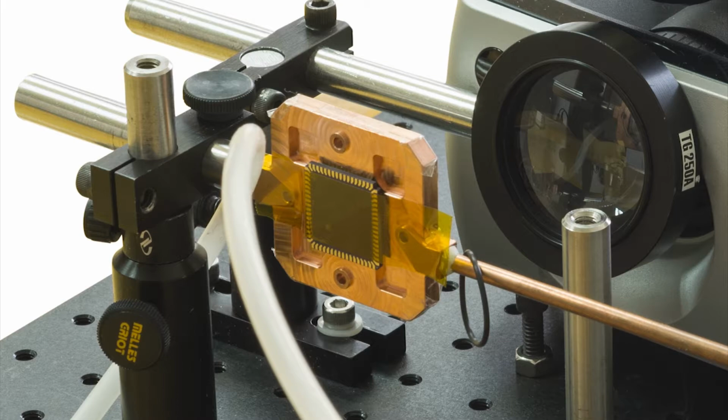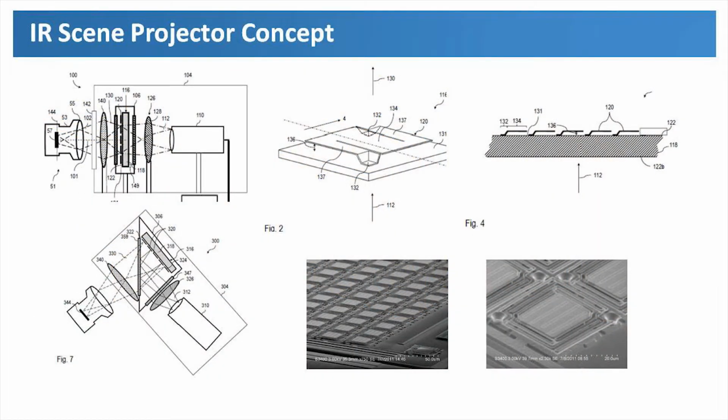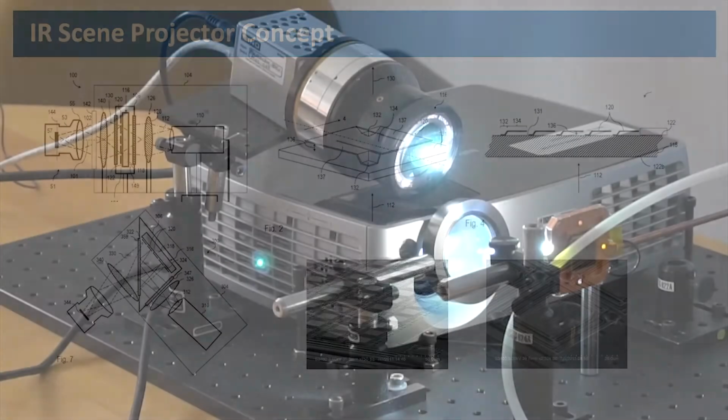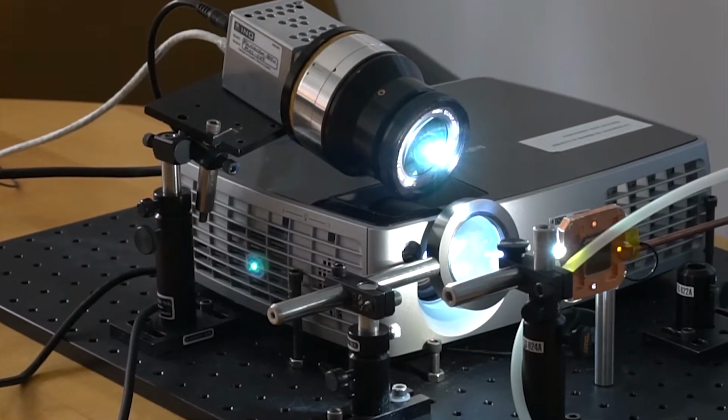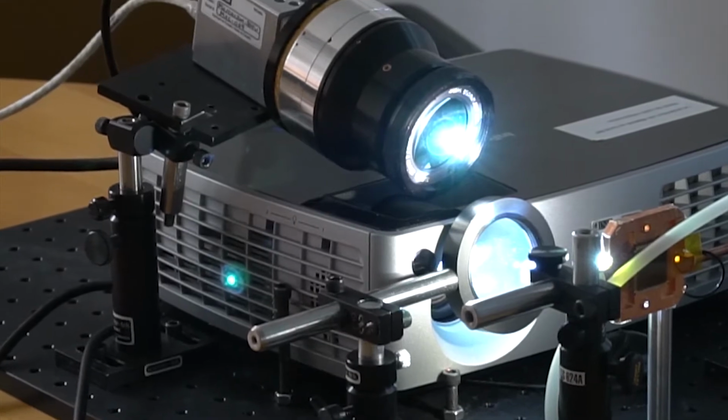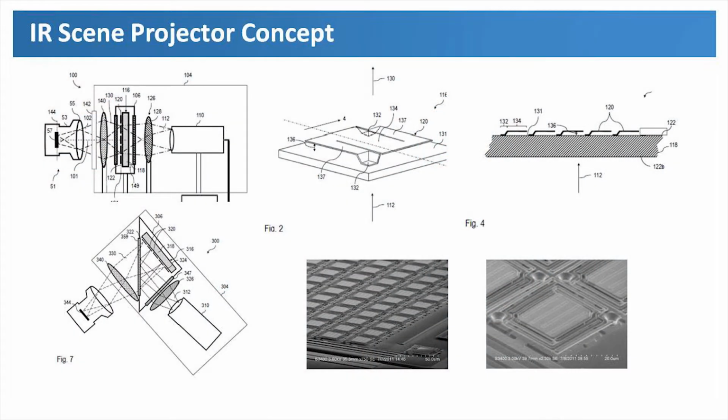So you have this micro platform which has a tiny size of 35 micron by 35 micron, a thickness of a fraction of a micron, and is supported by two legs which have a diameter in the range of a few microns. What is happening here? When the projector projects the visible image onto the array of these micro platforms, each of these micro platforms receives the visible signal. The visible light is absorbed by each individual pixel according to what is sent by the visible projector.